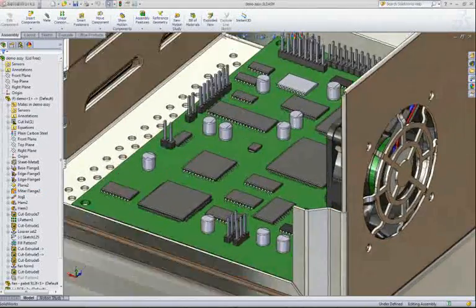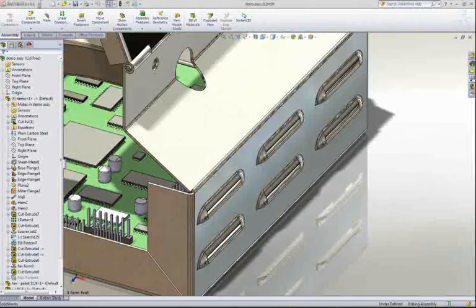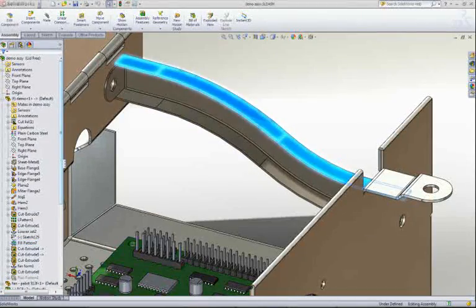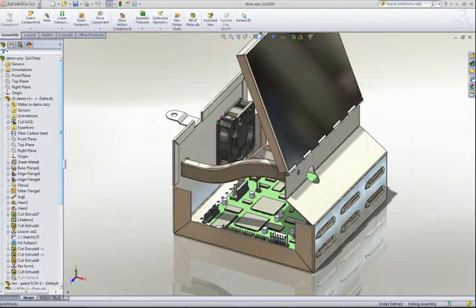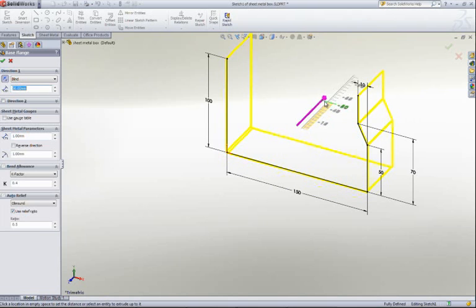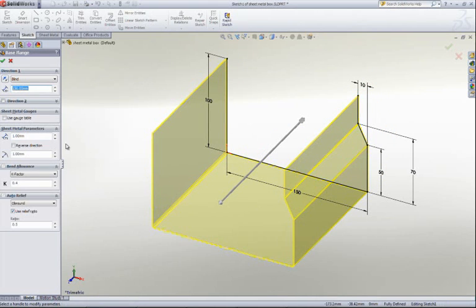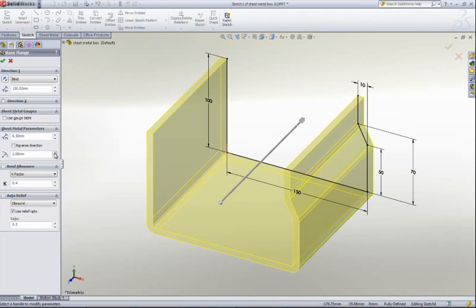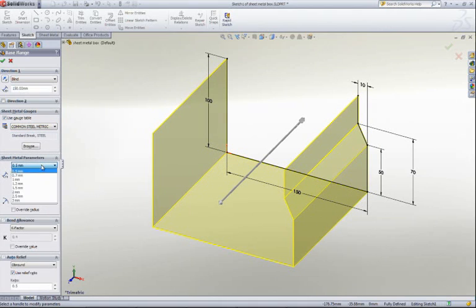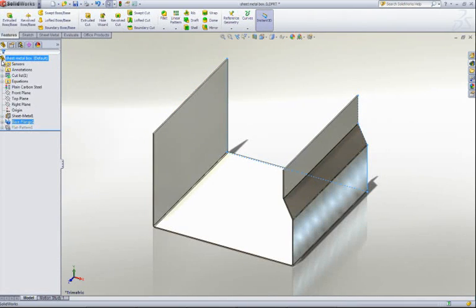Your CAD tool should not limit your creativity. You need the flexibility to create sheet metal parts in the manner best suited to the job in hand. We'll look at top-down assembly design later, but for now, we'll concentrate on the basics. Material selection should be your first consideration. In sheet metal design, we are often forced to adhere to certain requirements, such as standard materials and in-house standards for manufacturing and tooling. You need a simple way to make sure you comply with those standards. SolidWorks offers a customizable gauge table, which contains only the materials, thicknesses, and bend radii that are readily available in our shop, so there's no need to look it up each time, and you'll keep tooling costs to a minimum.